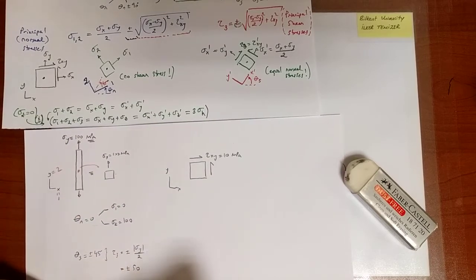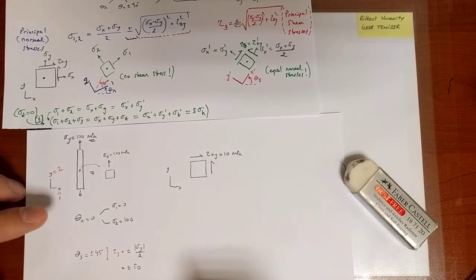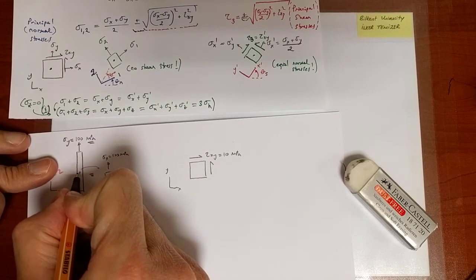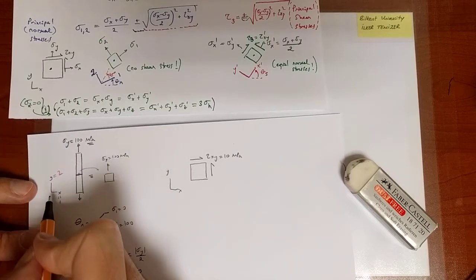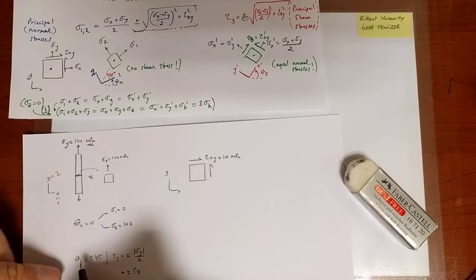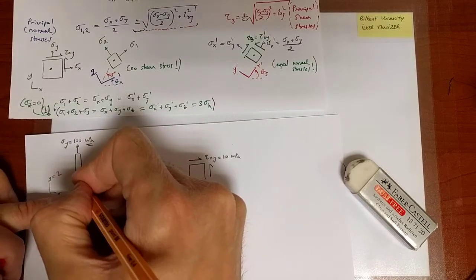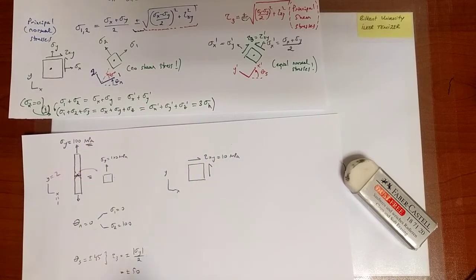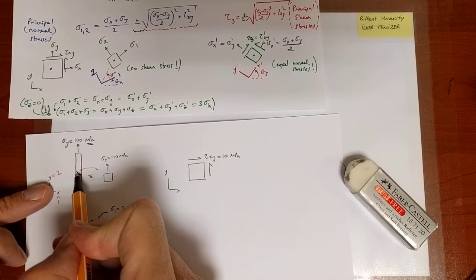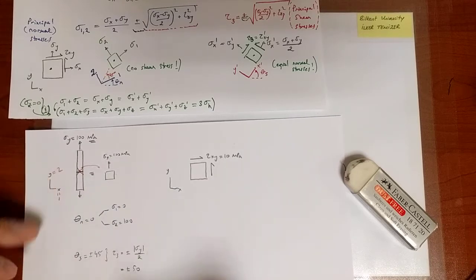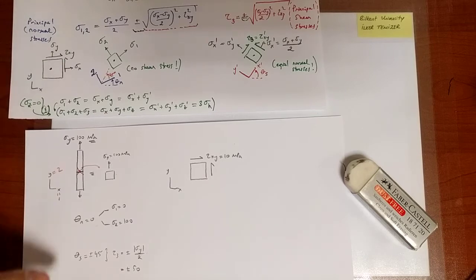All right, good. So the principal normal direction, that's the blue direction, is that direction. It's already a principal plane, so I'm drawing the line associated with sigma 1. And then there are principal directions associated with theta s, which is plus or minus 45, so either that or that orientation. Both of them are orientations along which the shear stress is a maximum. In one case it's a plus, in the other case it's a minus. So that's the first problem. Then we can go to the next problem.